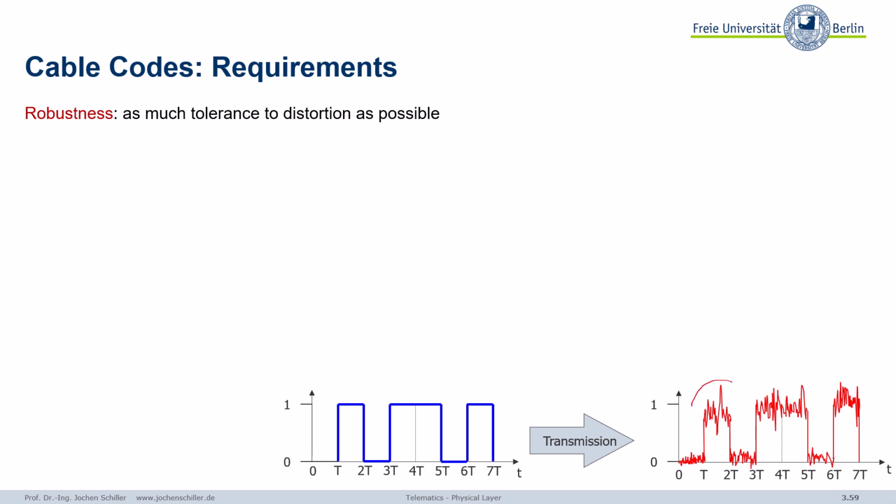And we have to take care that the noise is not too strong, so that we do not flip bits. But as you see here, if we insert a certain threshold, we still see, okay, that's obviously, for example, a 0, that's a 1, 0, 1, 1, 0, 1. Perfect. Although we have noise, it works.